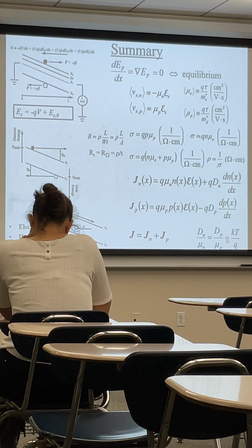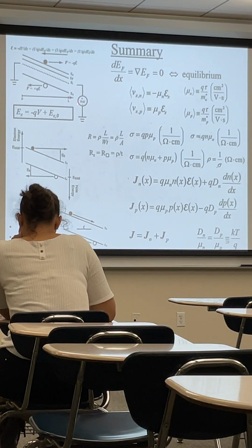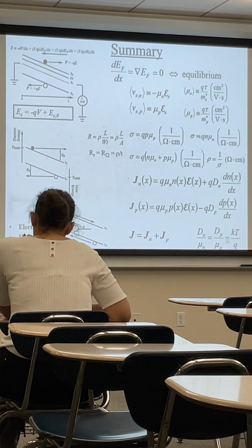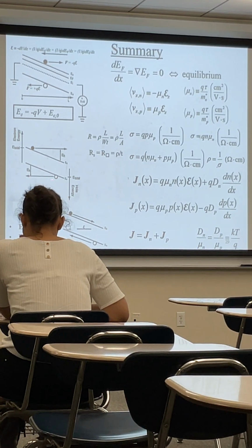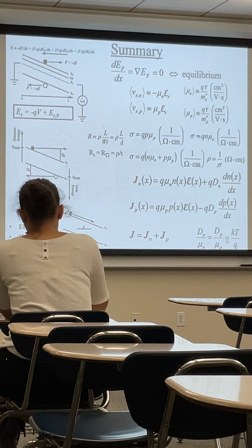Basically it can tilt the band diagram, and this tilting direction is related to the position of the applied voltage. Positive voltage pulls down the band. Also you need to understand how to calculate the kinetic energy and potential energy for electrons and holes.